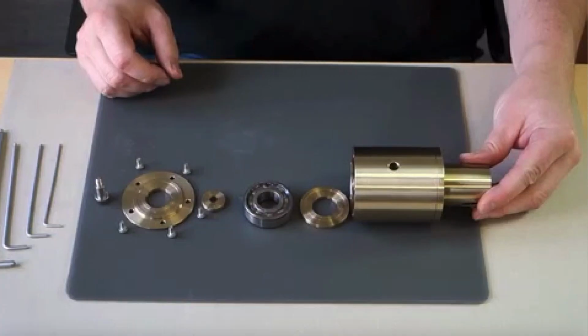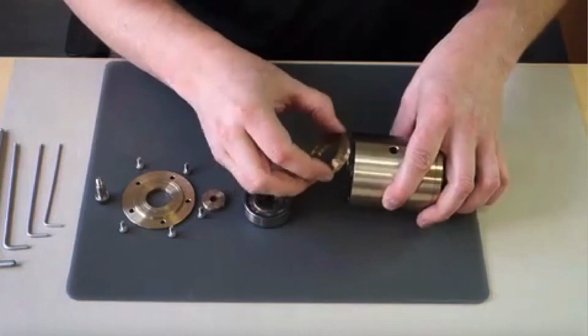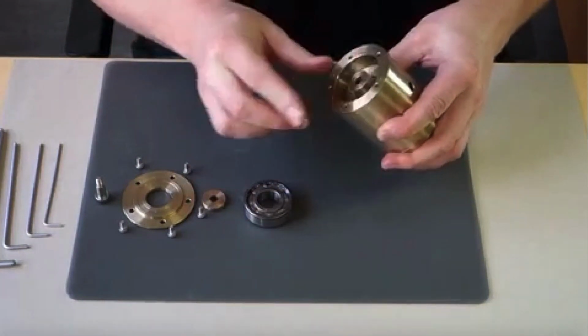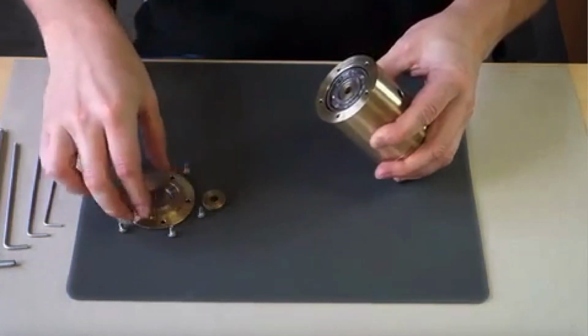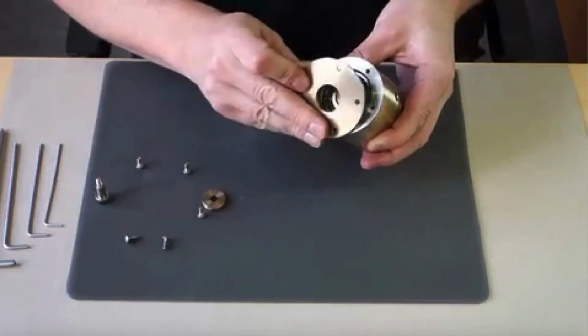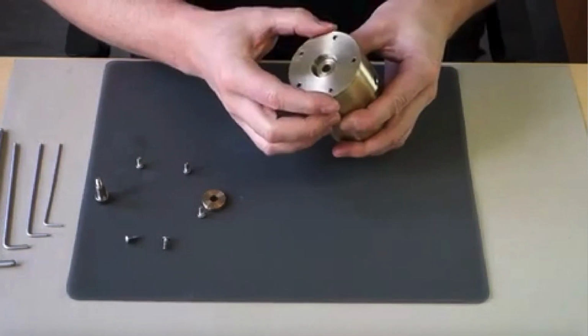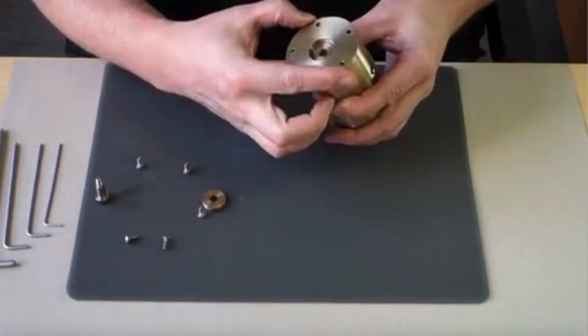Okay, this is the washout test. So that's the apparatus, that's your bearing, and again, you've already loaded it with grease and weighed it at that point, and you assemble it in here, and you see it's not sealed or airtight. You can get into the middle areas where the water's going to try to intrude.